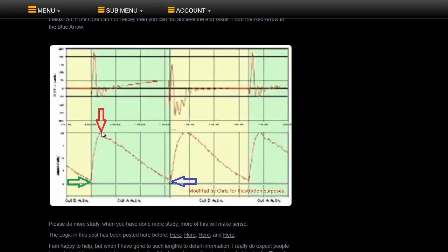Okay, so it's the same deal. Both devices use electromagnetic induction. They're both exactly the same processes. There's no difference, but the difference is in the form of work which is input. Again, current to a transformer is the work, and to a generator it is the shaft torque, the rotational force on the shaft. It's the only difference in work.